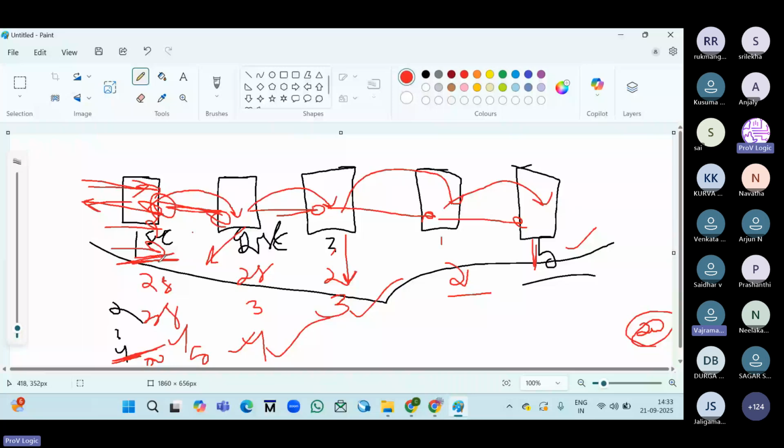Each step will do one small part of the work, like fetching, decoding, executing, memory access, and write back. So in cycle 1, it'll do instruction fetch. Cycle 2 will do instruction decode, where, if we take add as the example which we have taken, add R3, R2, R1, get the instruction from memory and put it into the instruction register. All of this completes in multiple short cycles. You have a faster clock, and each step is shorter.